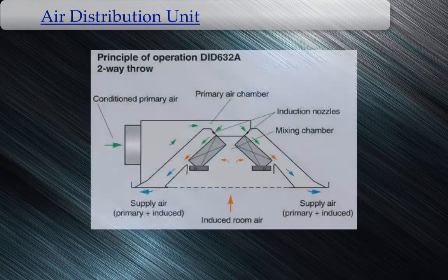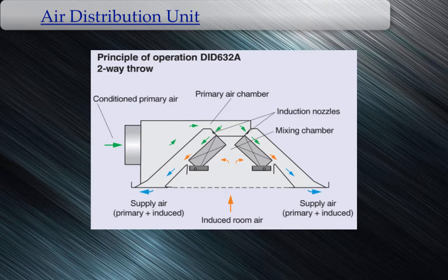Parallel to the DOAS, an array of active chill beams will be recessed into the plenum of each room. The active chill beams function as the primary system to handle sensible heat loads within the space. This is of primary concern for a system that runs parallel to a DOAS for its nature of decoupling the sensible and latent heat loads.